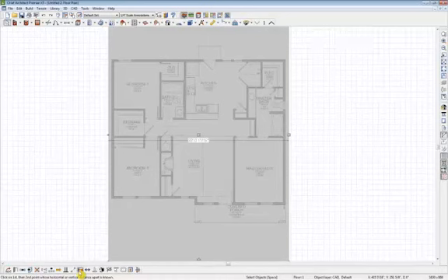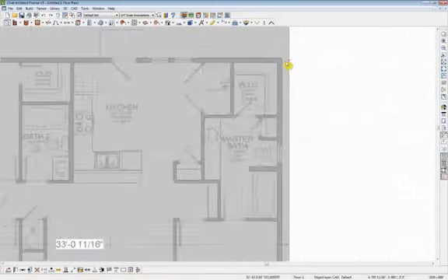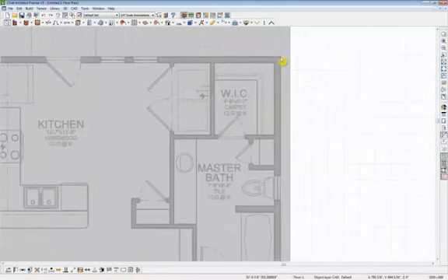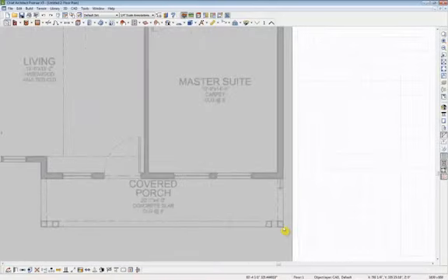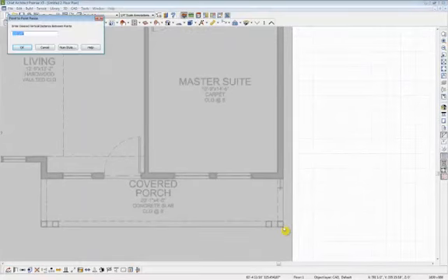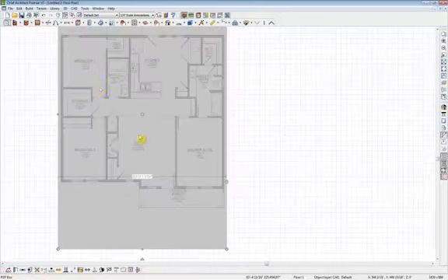So to begin with, I'll select this option, scroll in a little bit, and select the top corner, then scroll into this bottom left corner and click. I'm making sure to click exactly in that corner, and it will immediately open up this resize dialog, telling me what the existing dimension is. My desired vertical distance is 404 inches. Select OK, and it will vertically resize my image.